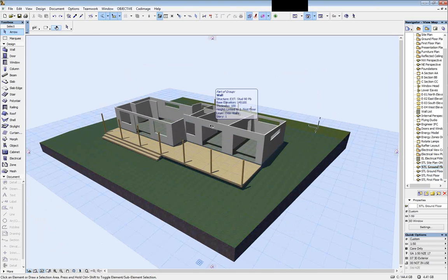So there's additional software available. It's covered on page 36. These are some of the ones that we were advised by our 3D printers that are quite good. And basically they analyze your STL file for these issues. So they try and find any holes, cavities, or items that are too small that the 3D printer will struggle with, and can clean it up that bit further. Although all of that can easily be managed via layer management and model view options in ArchiCAD. Just save the view of the part that you need and print it, and you should have no problems.